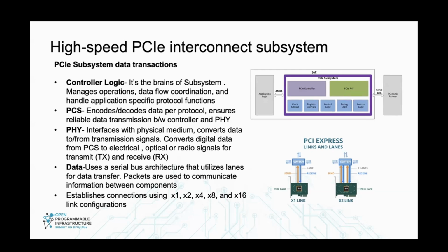This is a layer which is sandwiched between the controller and the PHY. What it does is it encodes and decodes the data which is coming from the controller side and makes sure that it's more reliable and understood by the PHY.